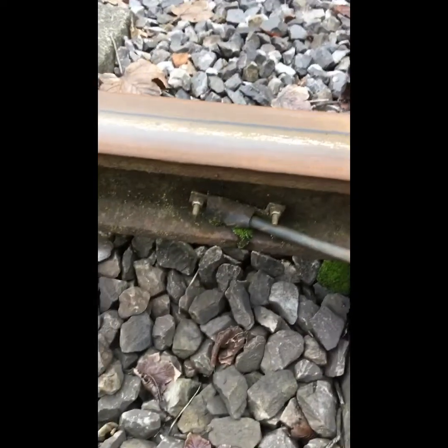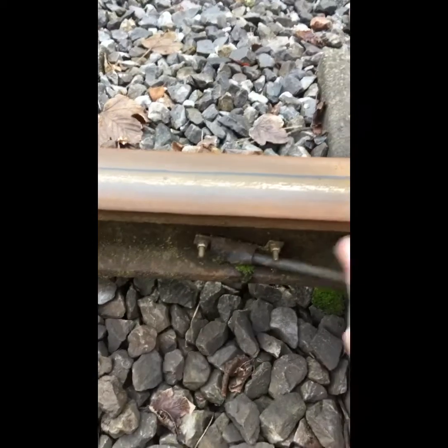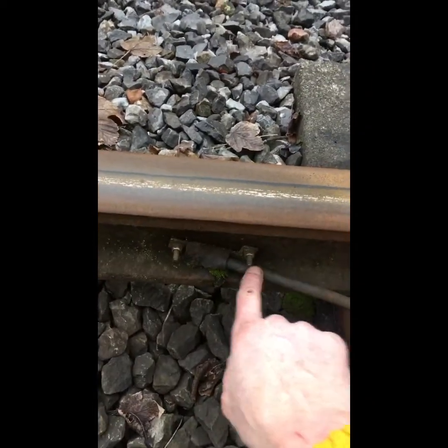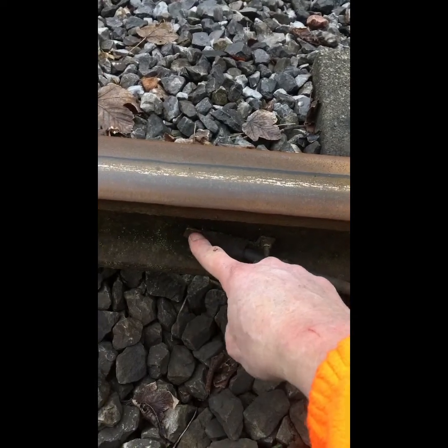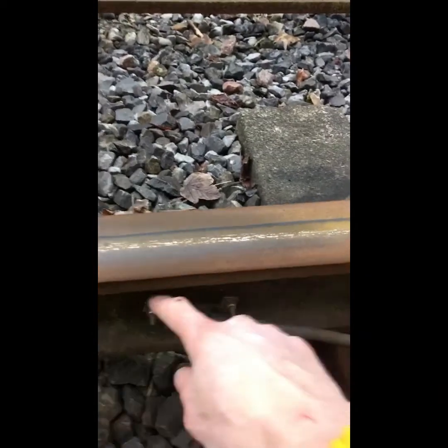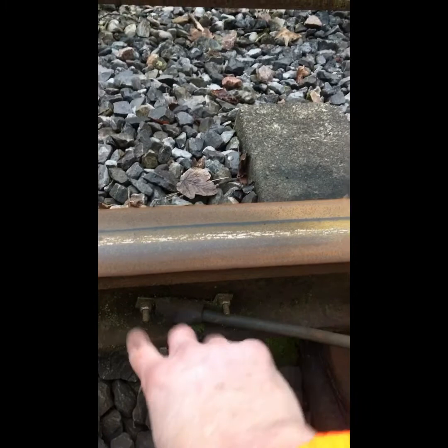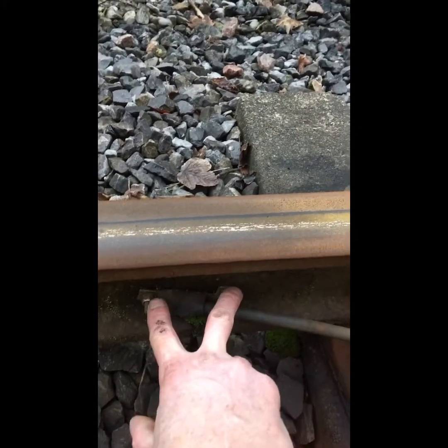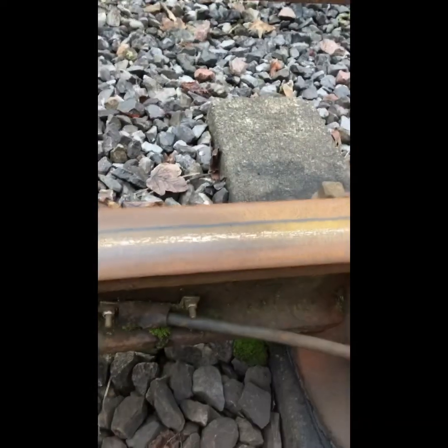These are our track feed leads and our track relay leads. So at either end you will have these, and what they simply are is the incoming track cable terminated onto a crimp which goes here. There are two galvanised pins which go through the rail. They're hammered into place. Some back nuts which go on, non-locking back nuts. Tighten them up, and then you put your L bracket on, as we call it, the L plate, which goes on to the rail. And your crimp goes round, and then your locking nuts.